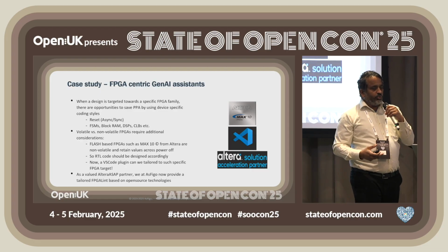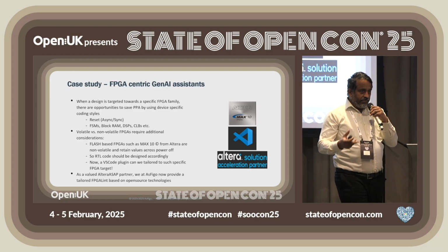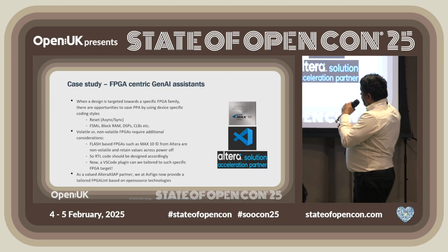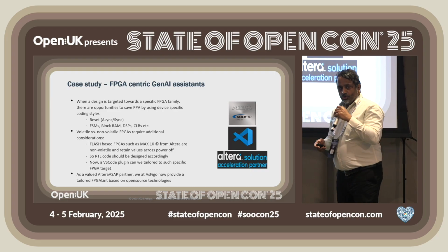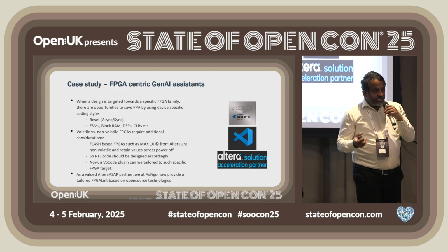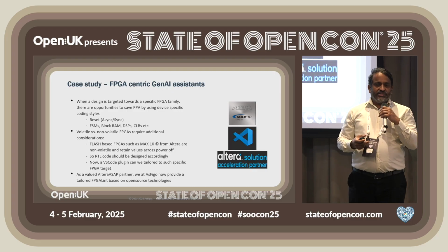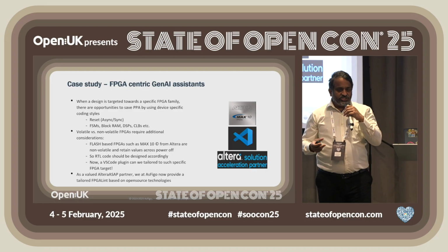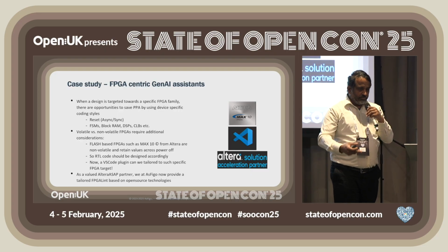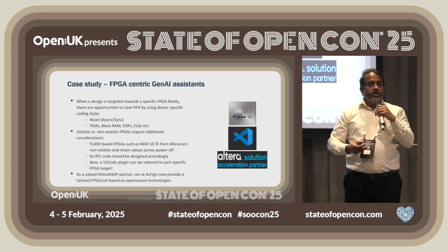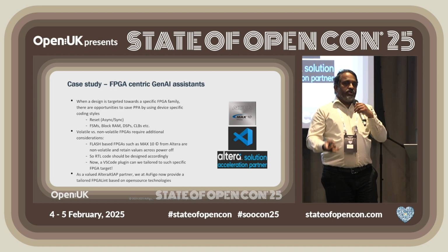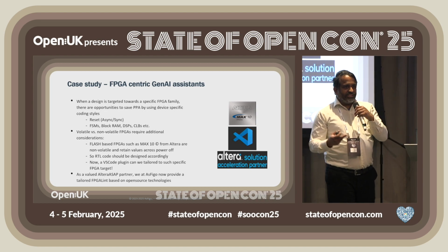With FPGAs, you get this idea of power-up. And adding on with the flash-based FPGA, you also get a retention for free. What is that retention? Essentially, when you power down, let's say with that system you were taking a picture and the DMA wasn't transferred, it actually is powered down. When you power up, it's going to come up exactly in the same state.